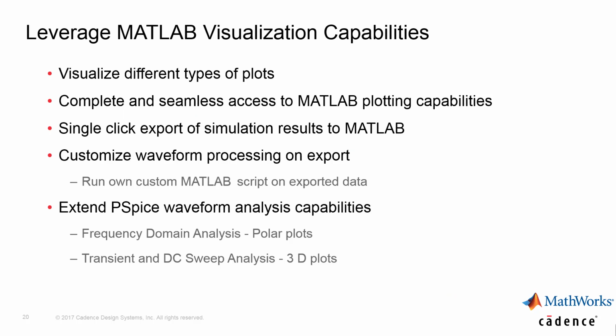So let's talk about some of the capabilities that are available with this integration. For example, you can visualize different types of plots in MATLAB. You can actually take the data and visualize the data in a polar plot, 3D plot, or a Nyquist plot. Users also have a complete and seamless access to the MATLAB plotting capabilities. You can export the PSpice simulation results into MATLAB with a single click. You can customize the waveform processing while you're exporting. You can even run your own MATLAB scripts on the exported data.